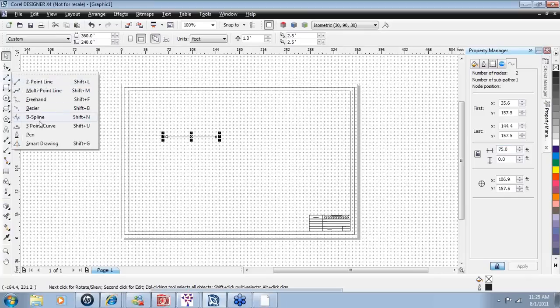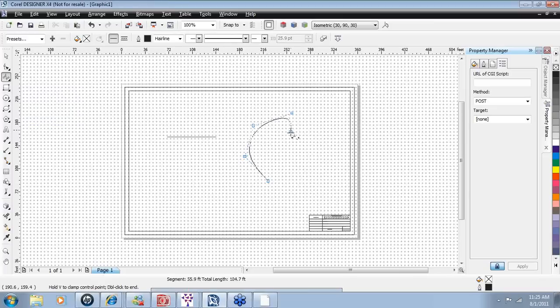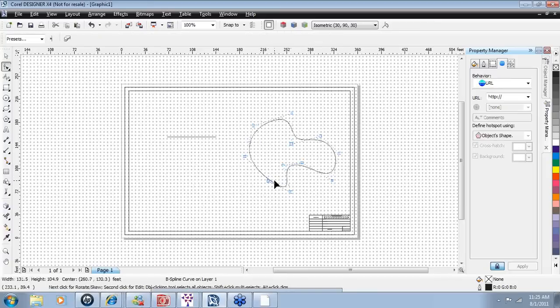Let's just go back into our curve line. To draw your bed lines, we're using a B-spline tool. This allows for you to bend and stretch, move this line like elastic. If any changes had to be made, we can double tap on this line, and you can further manipulate, which is outstanding. So many of the design applications, design programs that you've worked with in the past, they don't give you this flexibility. You end up with very jagged bed lines.